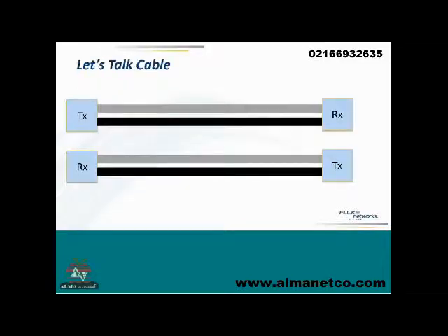So let's talk about cable. Let's talk about transmission line theory. So the way cabling works, in most instances, this is a simple example. This is, say, a good example for 10BASE-T. You've got two pairs. The gray line indicates one wire and the black line represents another. You've got a transmit pair and a receive pair. And obviously, the transmit pair at one end is the receive pair for the other end.